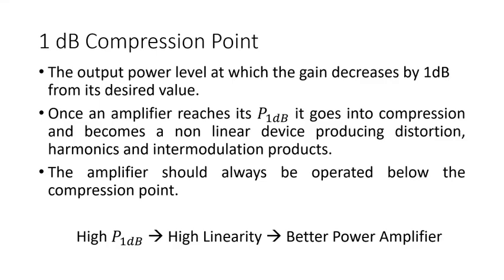intermodulation products. So for any amplifier, you should have a high 1 dB power point. If the 1 dB power point is higher, then you will achieve higher linearity and that will give you a better power amplifier.